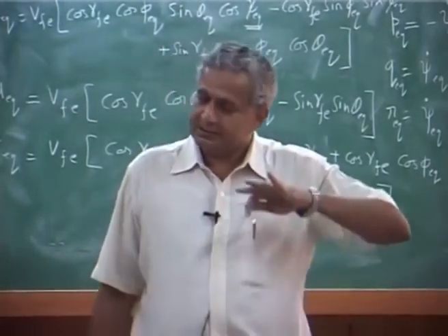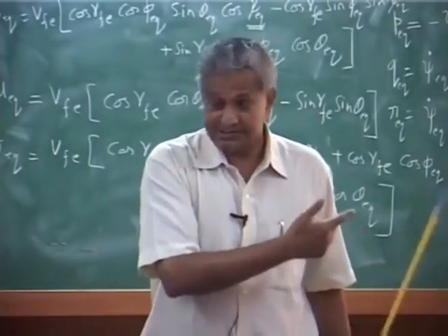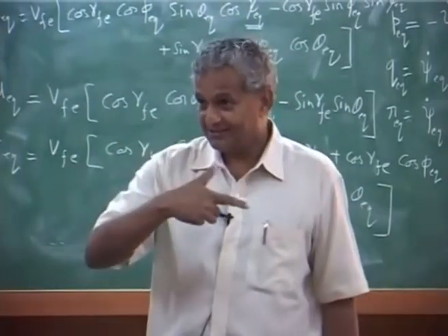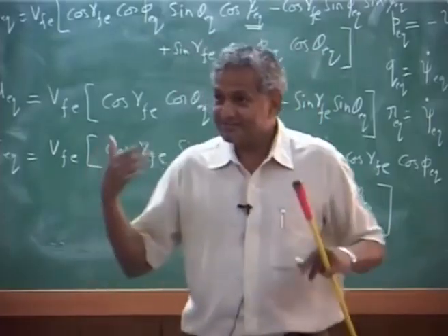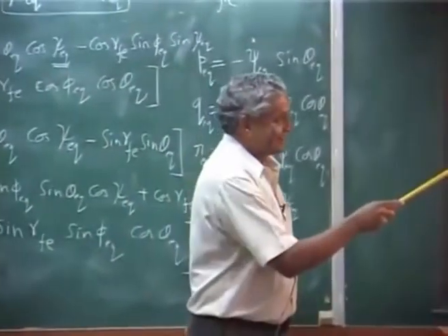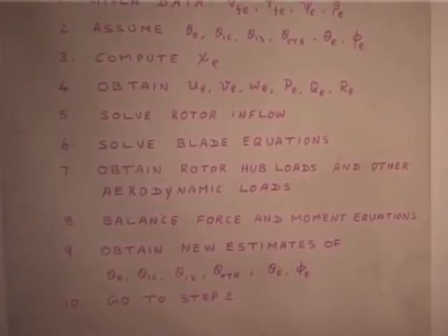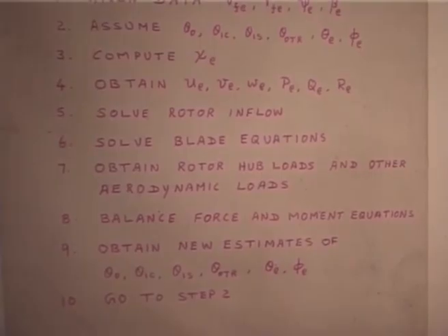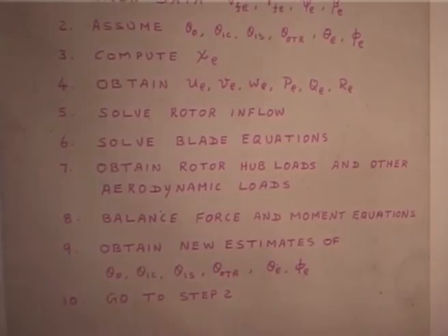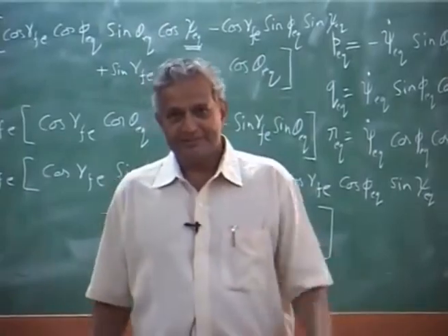Once it is done, then you can say okay, these are my loads, and if you want to include a stall model, please understand when I get the aerodynamic load I should have a stall model for the blade. All those things must be integrated in this part, I cannot have a closed form expression. So, that is why the aeroelastic problem is part of the flight mechanics problem. It is not an independent problem in helicopters, and if you are doing this kind of maneuver, this is a real challenging problem. Okay. I think with this we close.